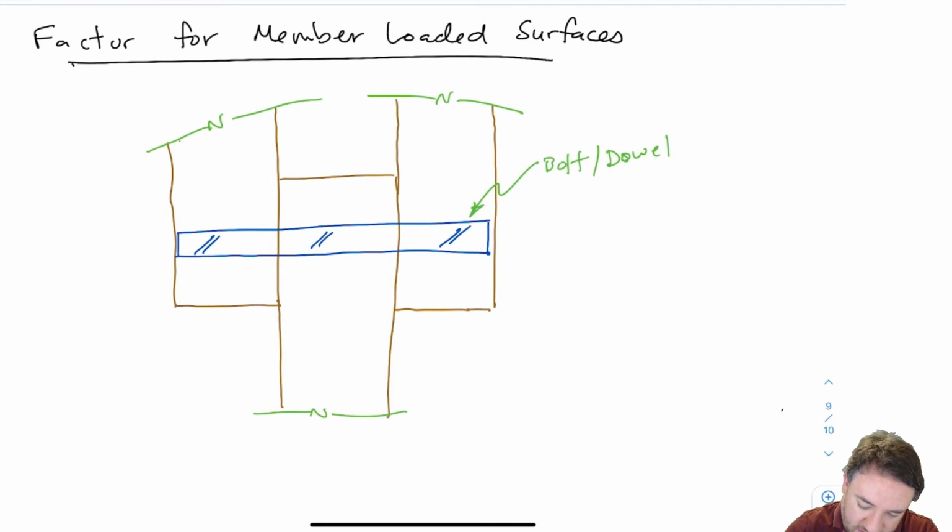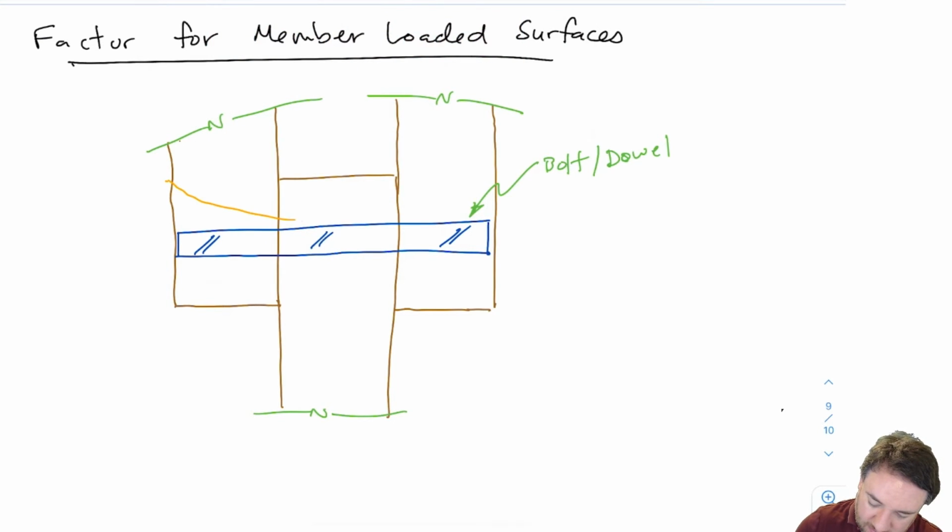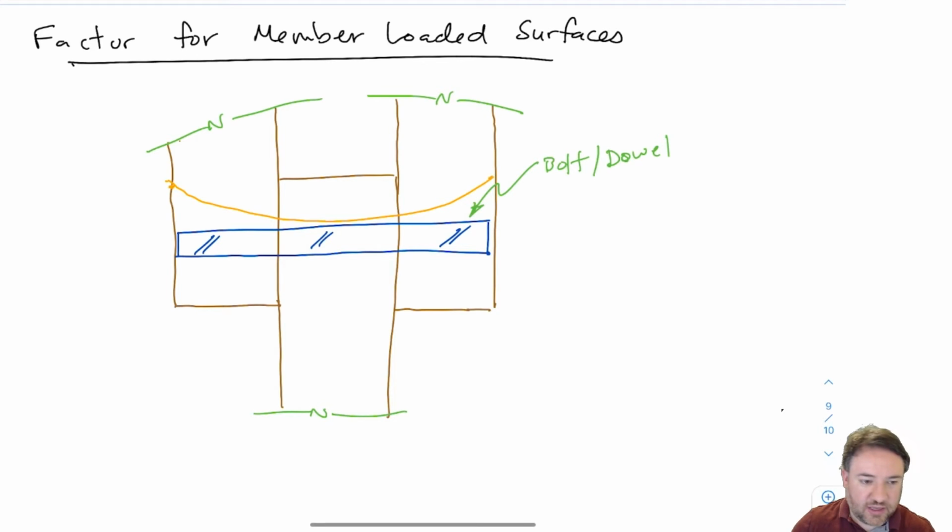Okay, so when this bends, you can imagine, we're going to get some bolt bending shape. At the end of the bolt, we're basically not going to have that much load because the bolt is flexible. So when it's bending, at the end, I'm going to get less and less stress as I get toward the end of the bolt.